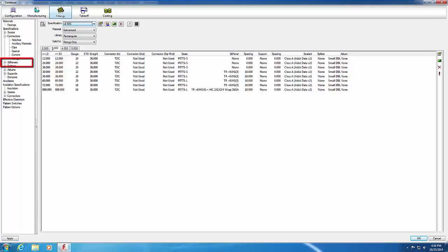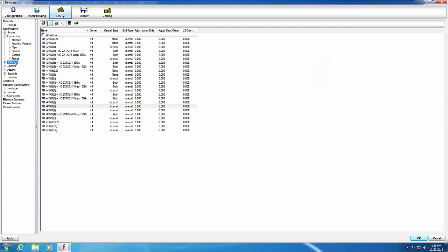Return to the Stiffeners menu item. Right-click on any stiffener item and a shortcut menu appears. Edit is the same as double-clicking on the item. Breakpoints directly opens the breakpoint tables for the item. Change Group enables you to organize stiffener specifications into groups. Print opens a print preview window with the selected stiffener specifications.